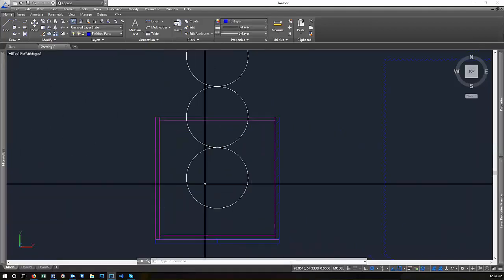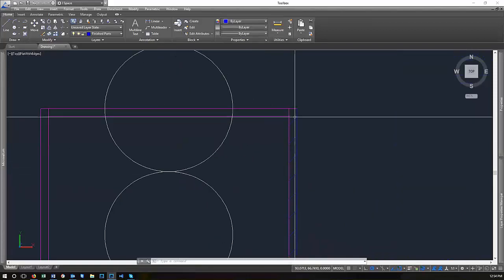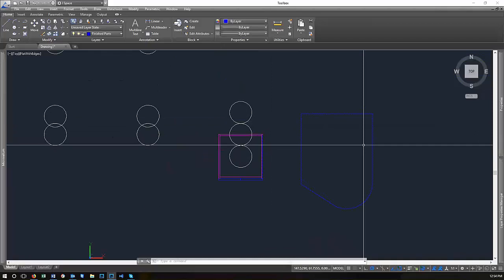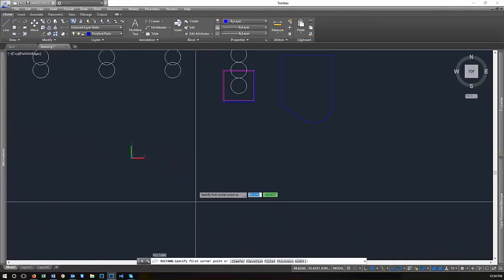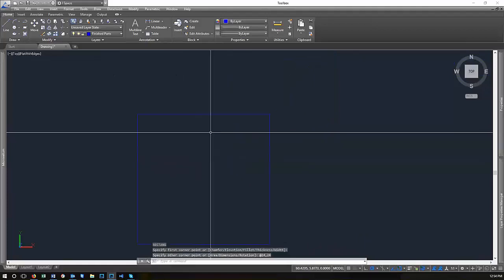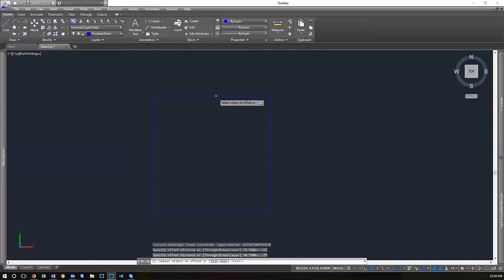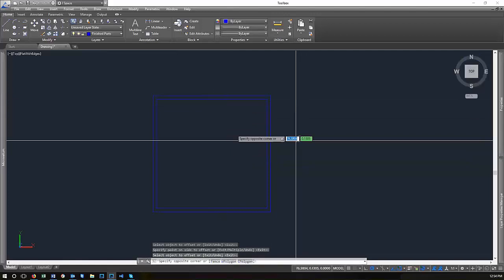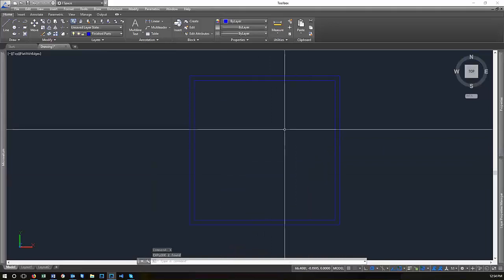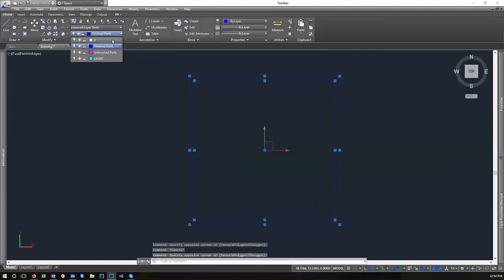This is the situation that I was talking about where you could more easily lengthen or shorten lines. So let's draw another square, and let's do another 24 by 24 and offset 0.75 and offset in. Okay, so let's explode these again. So that's a basic layout for any cabinet. It's pretty standard, but let me change all of these objects also to white so it's a little easier for you to see.